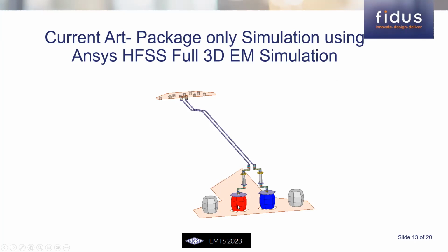But when we look at the BGA bumps, they could have a pitch of 1 mm. They're about 600 microns tall, about 500 microns wide. These are big structures. And placing a port at a reference plane near the BGA balls to the PCB interface is questionable. This will violate some of the fundamental limitations of S parameter definition. Yet this is what is done when we ask for a package S parameter model. You take this model and integrate it with the rest of the PCB and proceed. It's a very good approximation up to fairly high frequencies. But if you're talking 50 gigahertz plus, the approximation tends to break down, and you'll need to consider the entire structure as a whole.